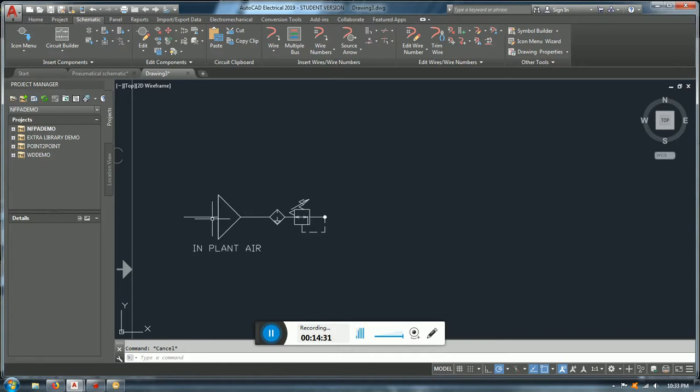coming from here, but or whatever pressure, but here you really say, like, you know what, here it sometimes gets 100, but sometimes it's going to be reducing between 100 and 90. Why do I want constant? I don't want changing, because things are going to change. The cylinders, they're going to work faster or with more force. You don't know really, and you don't want these kind of issues. You want to be constant, you want to know what is going on all the time.